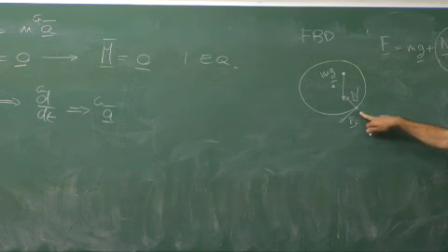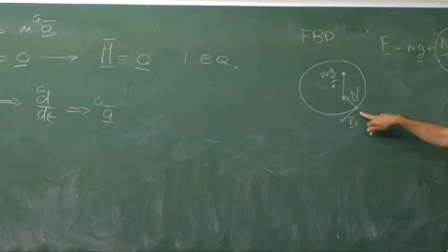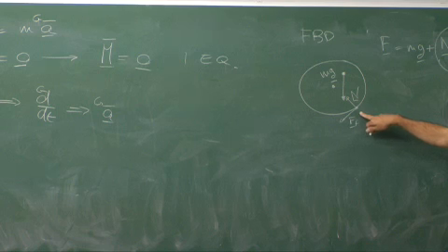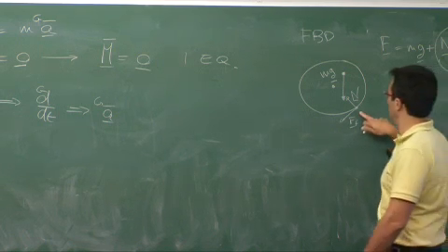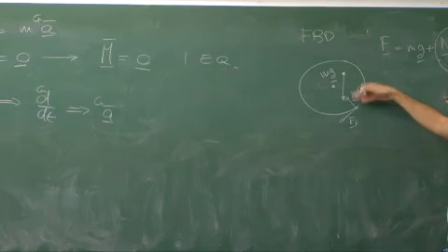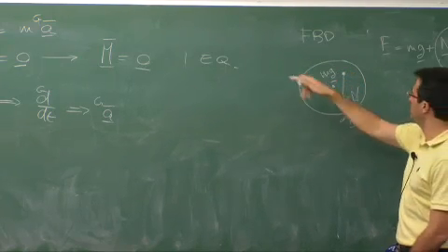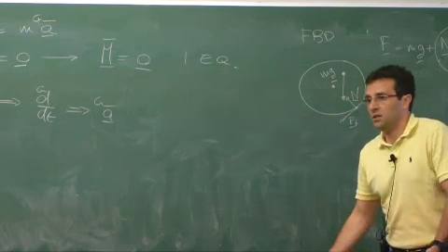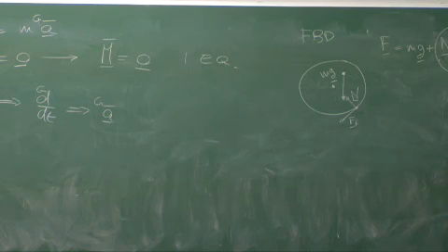And I really don't care about the end result. I told you I don't care about the algebra. I just need to see that you know how many equations you need to write in order to get rid of the unknowns, right? So if you tell me that, for example, this is sufficient, that is not right. You can't get an equation of motion from that one. If you do moments with respect to center of mass equals 0, I don't even see the theta double dot appearing. How can you get a differential equation of motion from that one? Or if you stop at F equal m a bar, you still have these two there.